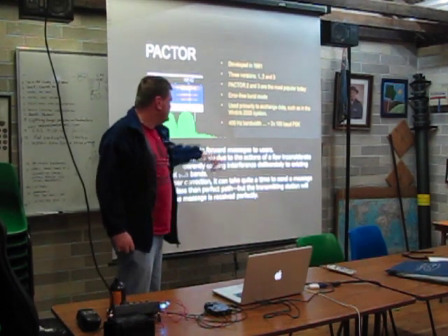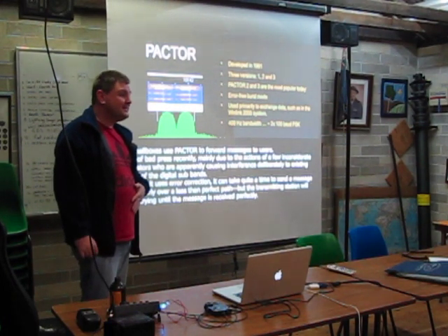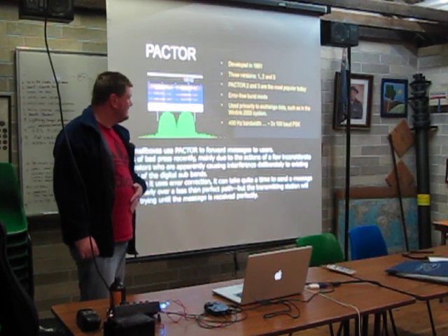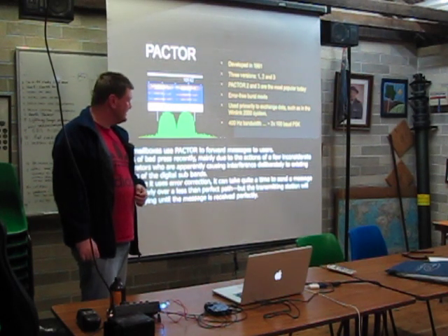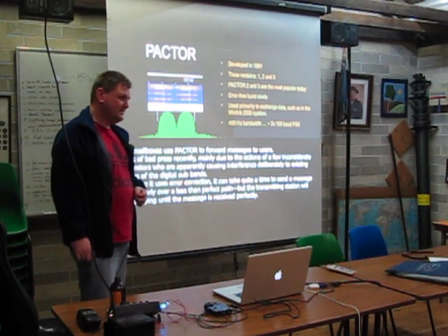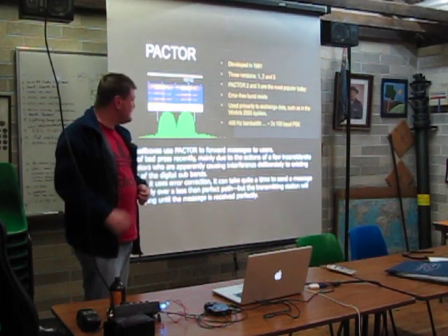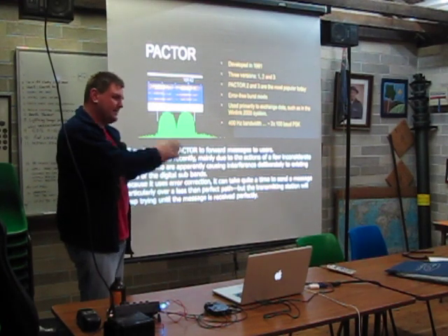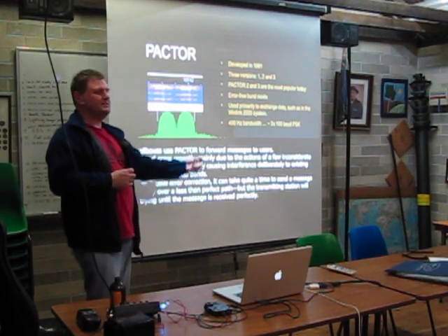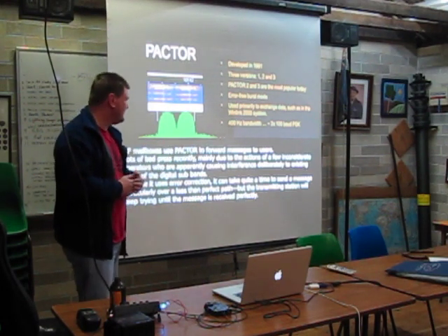So they have this WinLink 2000 system where you can set up an account. I should point out there is a Pactor 4 now, and also Pactor and some of these ARQ modes. You send the thing and you get acknowledged that the packet was passed, so it goes back and forth, whereas with PSK or RTTY, it's one way. That's the major difference with these things. Yeah, so some of these modes, that's true. They'll send something, and then the other end has to acknowledge and send back a transmission. So it chirps back and forth like a bit of a cricket or something.